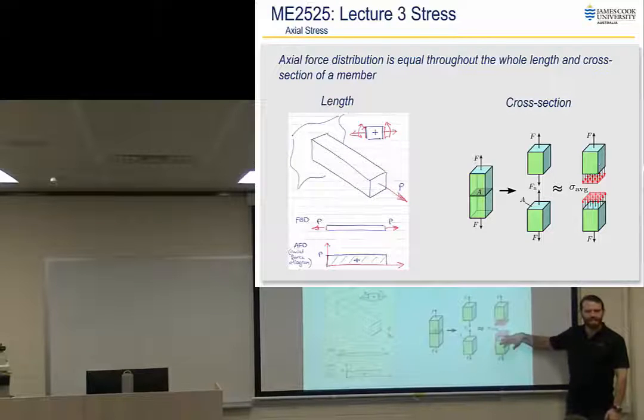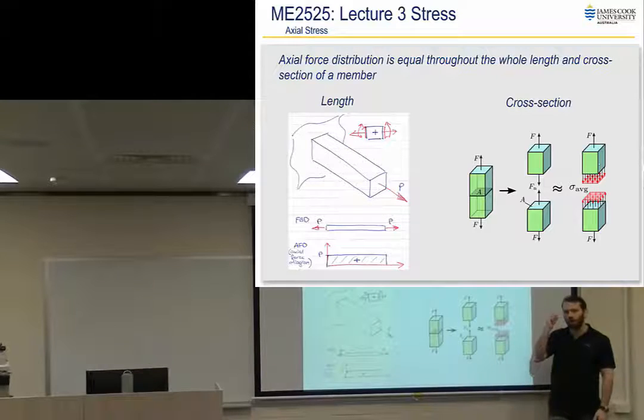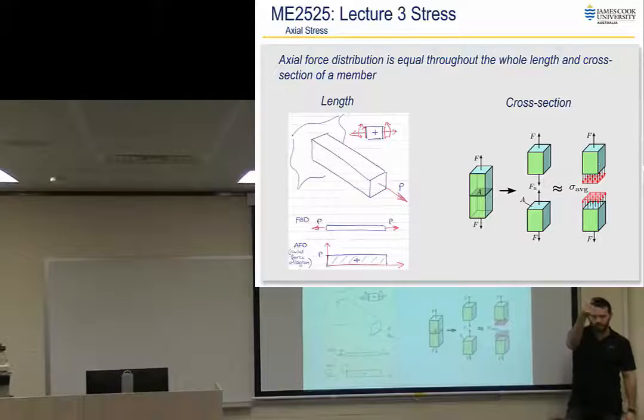It's a nice, flat, even distribution of that stress. So if I was to take an element at this corner, or an element at this corner, or back two corners, or anywhere in the middle, the stress element would look identical. All right, so infinitesimal element, we're talking theoretically atom dimensions, but we draw it whatever size is easy to draw. But it's assuming that it's a point in space, not an actual volume, when we draw one of those elements.